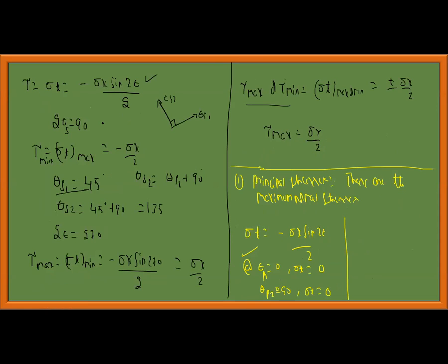Next, I will go to sigma t. I will find theta s1 and theta s2, substitute once again into sigma t, and get tau max or tau min. But always remember that the maximum shear stress planes are also accompanied with average normal stress. In order to find that, I will substitute the value of theta s1 in sigma normal, which is the normal plane. At theta s1 equal to 45 degrees, is there any average stress we should find out? This is for your clarity.